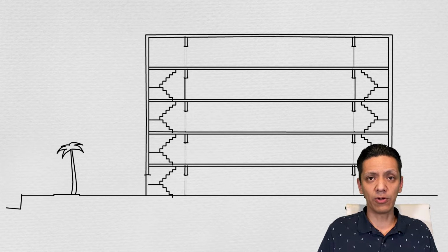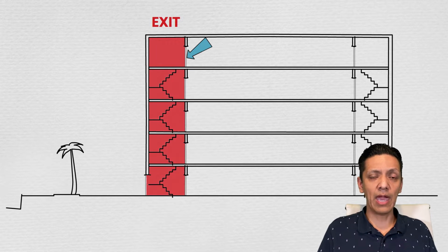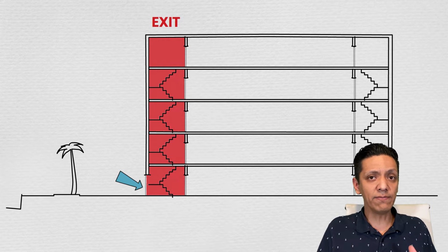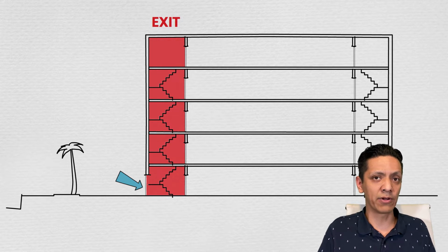Per the building code, your exit starts when you enter the exit stairwell, and it ends when you get to the exit that leads directly out. So that door that leads directly out is kind of part of the exit, but it's actually the very tail end of it. It's the end of your exit and the beginning of your exit discharge.